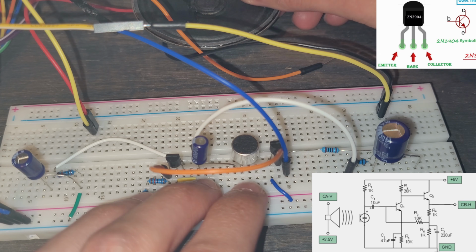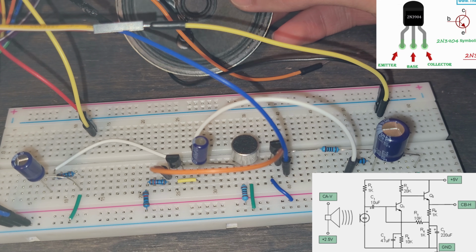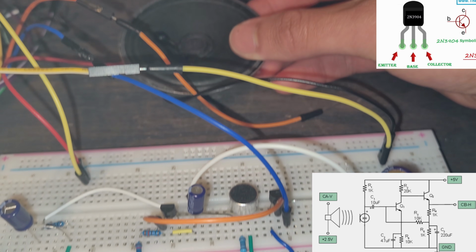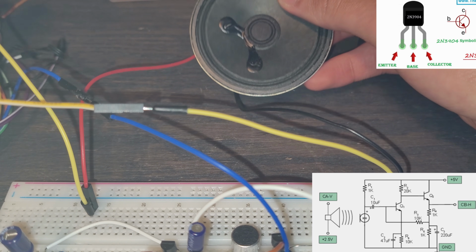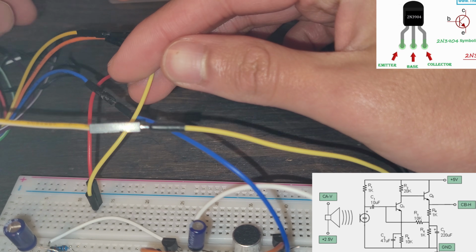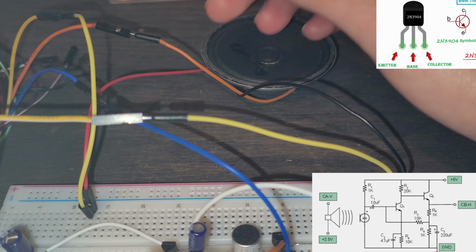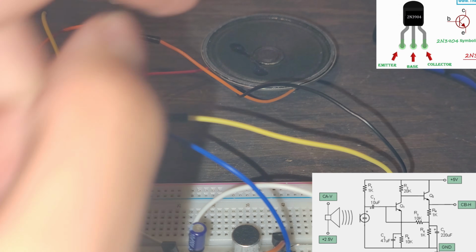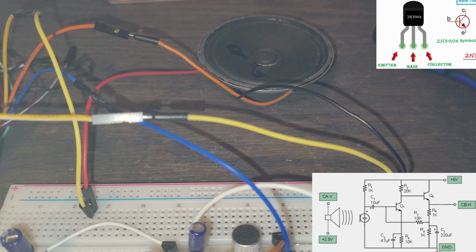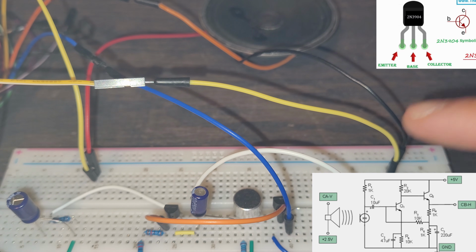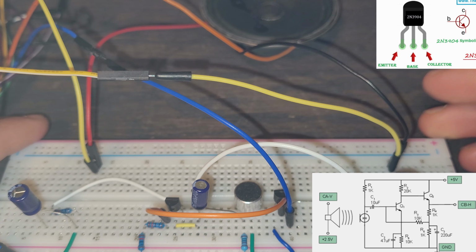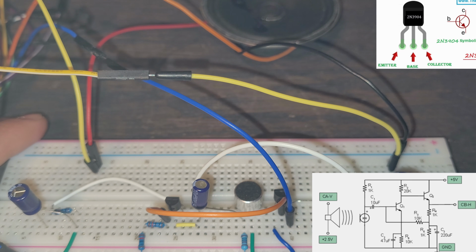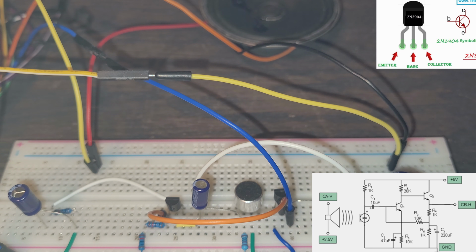Now, let's look at something else: our speaker. This speaker, we can see, looks like this, right? It has a red side and a black side. We want to have our solid yellow wire go into the red side of the speaker. And then the other wire, the yellow wire with a green or white stripe, is going to go into the black side. That's because we want to send 2.5 volts through it, and we want to make it emit a sound. That way our microphone can hopefully pick it up.